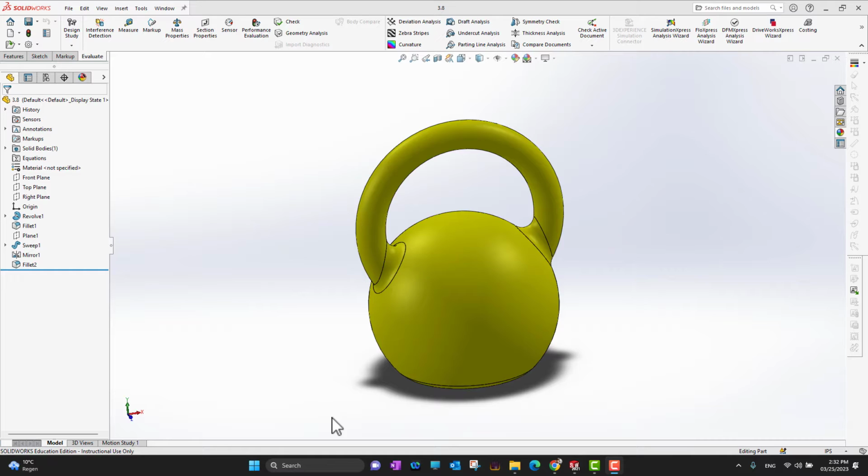In this video we are going to talk about the mass properties in SolidWorks. As we know, the weight of any part depends on the volume of the part or object times the mass density of that object. The mass density depends on the material type, so it is going to change from material to material. So let's figure out in SolidWorks how we can weigh a single part or a single body.